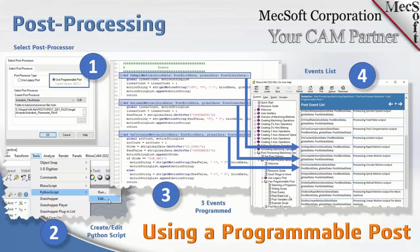There's on rapid motion as the event that's being handled, and there we're doing certain things. In this particular case, we're counting the number of linear motions that were being output. We're incrementing it, and then we're creating the format that we want to output. So that's what that event does. This way we can control the output based on all the various events that we encounter as the system is traversing the internal toolpath. So it's a very powerful system.